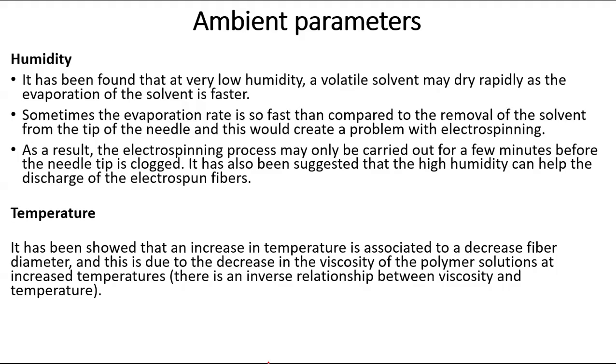The temperature: an increase in the temperature will decrease the fiber diameter. It is because it will decrease the viscosity. At higher temperature, it will decrease the viscosity. So therefore, you can expect a decrease in the diameter.